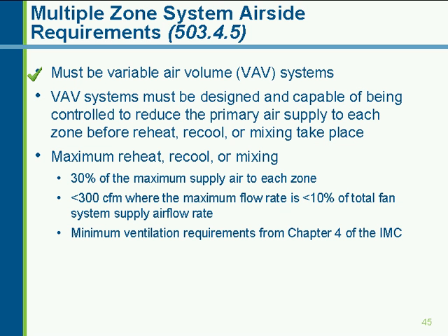It must be either 30% of the maximum supply airflow to each zone or less, less than 300 CFM total where the maximum flow is less than 10% of the total fan system supply airflow rate, or that amount can be up to the minimum ventilation requirements of Chapter 4 of the International Mechanical Code. So you're allowed to reheat as much air as required for ventilation purposes.